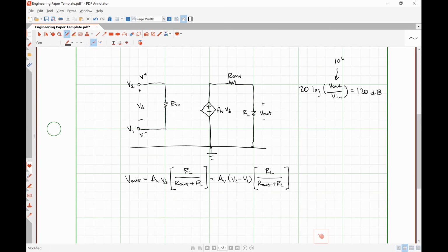Yeah, sorry, I didn't realize you guys hadn't had to deal with decibels yet. And then on the third one, volts per volt's easy, so you don't even have to do any conversion whatsoever. And for the first one, you said it was 200,000? Yeah, because it's a volt per millivolt, and a volt is 1,000 times larger than a millivolt. Okay. So that's why it's 200 multiplied by a factor of 1,000. Oh, okay. I did it wrong, but I did my calculations in MathCAD, so MathCAD did it correctly. All right. I see how that worked out now.